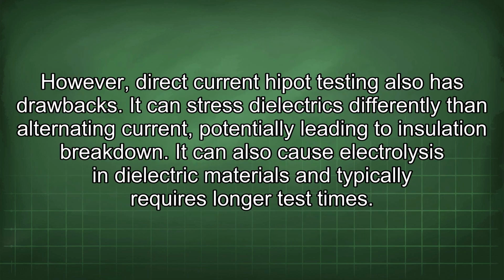However, direct current Hipot testing also has drawbacks. It can stress dielectrics differently than alternating current, potentially leading to insulation breakdown. It can also cause electrolysis in dielectric materials and typically requires longer test times.